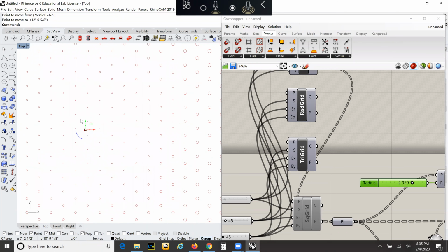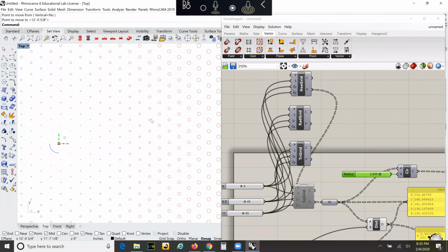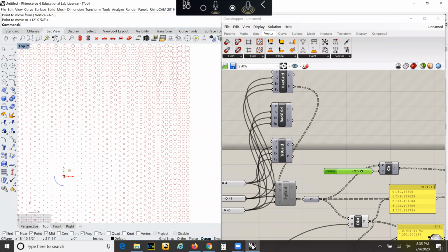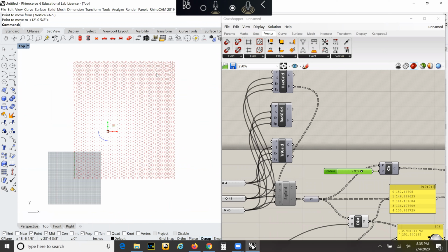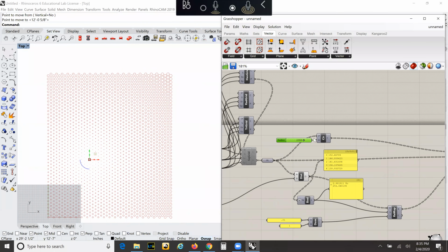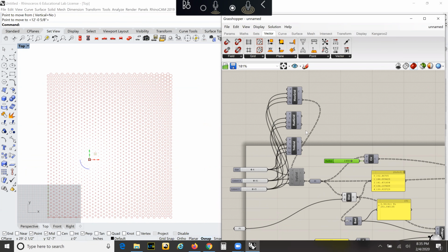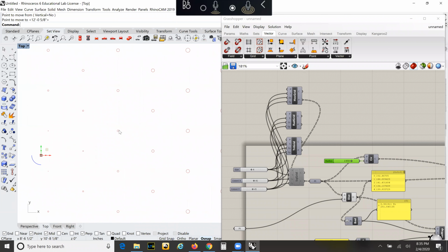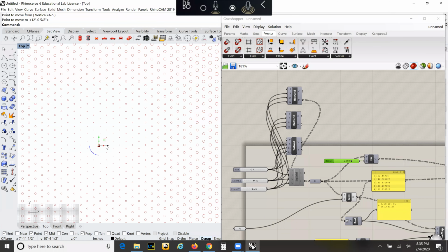Also, one thing that we can do is let's take the area of all these circles. Well, so there's an issue with what we just did in reality. When we go and send this to a fabricator, they don't want to CNC these little holes, and you probably don't want to get these holes CNC because they are microscopic.